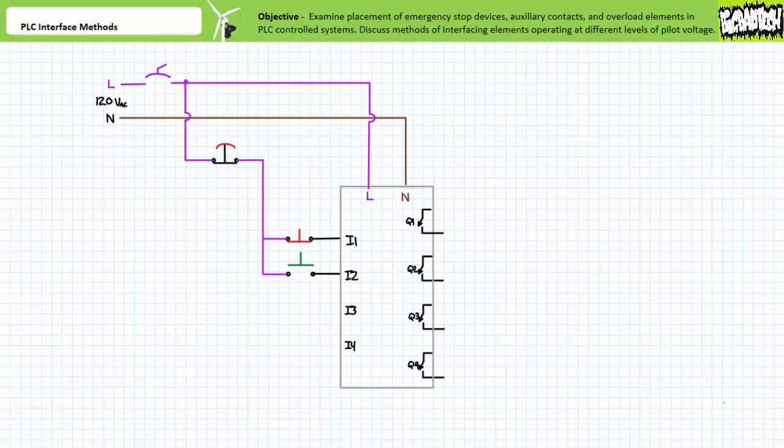If, however, the E-stop is in the activated open condition, the closure of any field input device will not issue a logical 1 to the PLC despite repeated attempts to do so. Wired in this fashion, the hardwired E-stop directly upstream of all field input devices has effectively severed all incoming communication with the outside world without the necessity of resorting to any program to do so. Note, as implemented, opening the E-stop would still keep the PLC powered up.